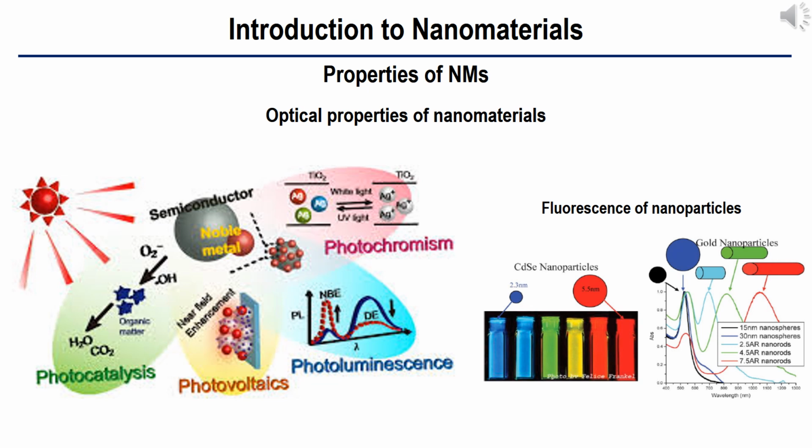Due to their small dimensions, nanomaterials have an extremely large surface area to volume ratio, which makes a large fraction of the atoms surface or interfacial atoms, resulting in more surface-dependent material properties. Especially when the sizes of nanomaterials are comparable to the characteristic length, the entire material will be affected by the surface properties of nanomaterials. This in turn may enhance or modify the properties of the bulk materials. For example, metallic nanoparticles can be used as very active catalysts. Chemical sensors from nanoparticles and nanowires enhance the sensitivity and sensor selectivity.